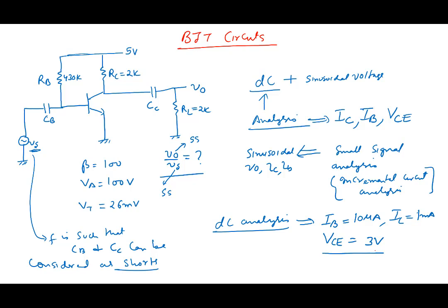Remember, the small signal analysis, or incremental circuit analysis, will be done by substituting the incremental circuit model for all the elements, right? So remember that the DC voltages will become shorts, the transistor will be replaced by the small signal model, and capacitors we are saying are short at that frequency.